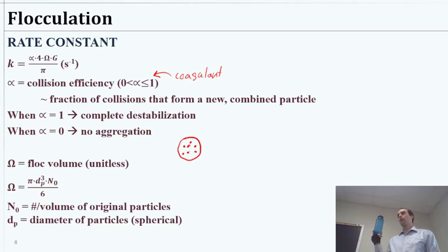Even if this was chock full of particles, very murky water, you could collect them and kind of measure them maybe, but it's going to be some small portion of the total water. So when I say flock volume, we are talking about the volume they literally occupy, but we're going to do it on a per volume basis. So it's going to be a volume fraction. What fraction of this bottle of water is made up of just particles? That'll be a pretty small number, and it is then going to be unitless because we did volume per volume. So it's actually